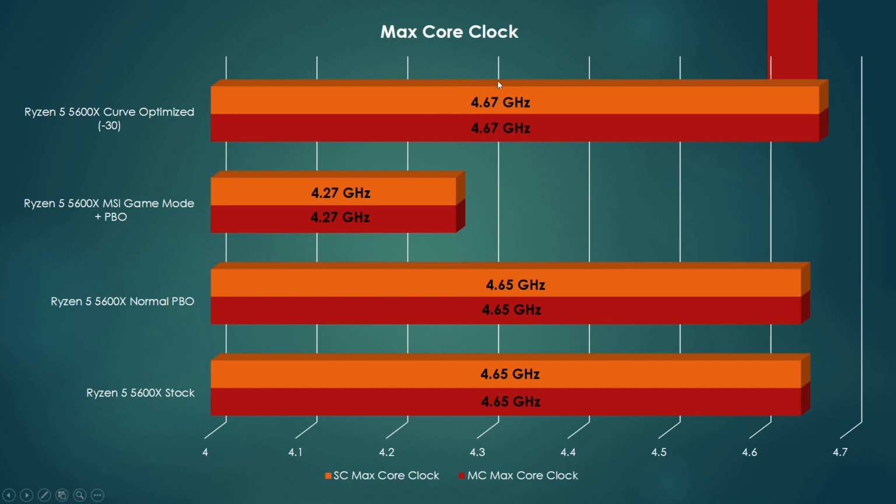With this configuration, now I'm confident that I can also boost my CPU to 5 gigahertz. But I'm not sure if Ryzen 5000 is efficient enough to go to 5 gigahertz. But the newer Ryzen 7000 CPUs have a working frequency of 5.5. So the main objective of this curve optimization is to reduce the power consumption and to increase the efficiency, resulting in lower temperatures. That is the real good thing about this curve optimization algorithm.